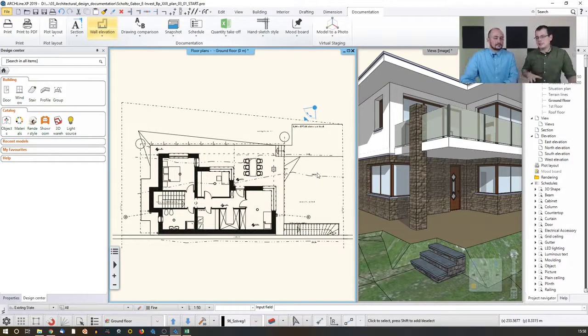One very important thing to point out, and that is something that we haven't done: whenever you are making an export, it's always good to export to subfolders. Because sometimes certain export formats, for instance OBJ, come with many additional files. So if you just export something to your desktop, then you might end up with hundreds of images and textures and things like that. So it's not what you want.